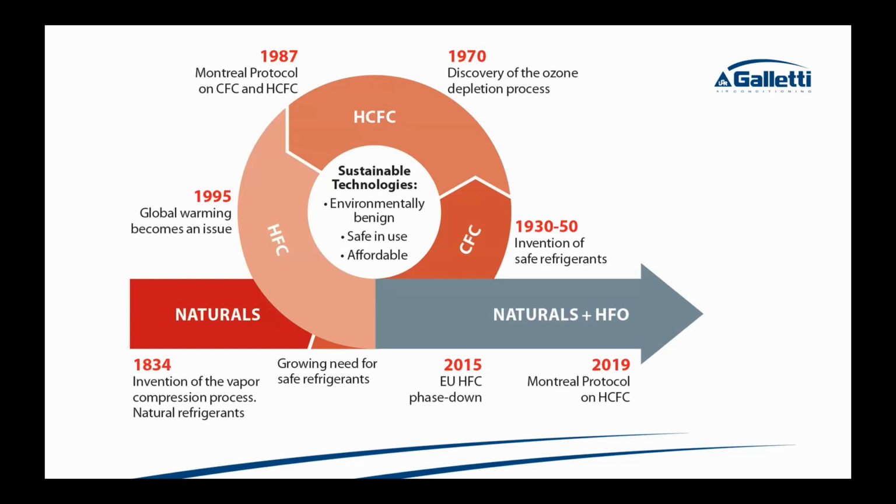And now that we're shifting away from HFCs, which in Massachusetts is actually quite recent, bless you. So for instance, this year, with chillers, there was what's called 310 CMR 7.76, which says that they were banning certain hydrofluorocarbons, one of them being 410A for chillers. And the only reason that I went down the rabbit hole on this one is because we have